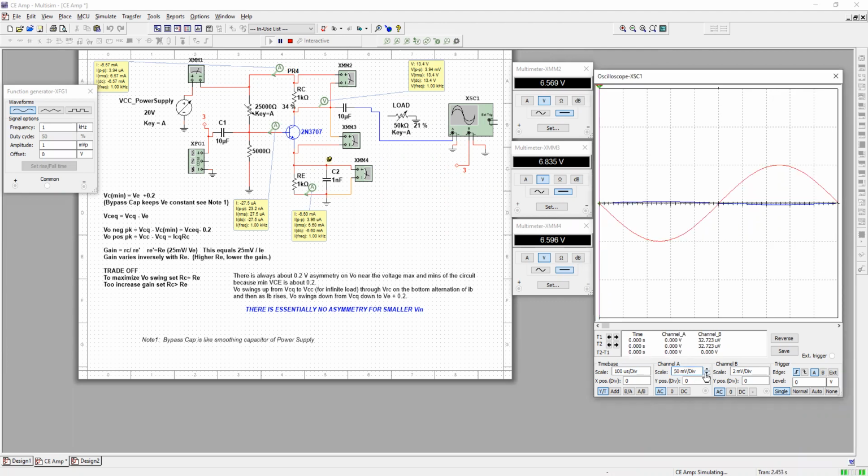Let's actually decrease our scale and see what it is. Wow, we have really dampened that output signal. Is it still giving me any amplification at all? It looks like unity right now. Not even giving me any amplification at all. What I've done is increased the impedance of the capacitor by reducing it. So the AC signal is finding a larger resistance here. It's not a short anymore.